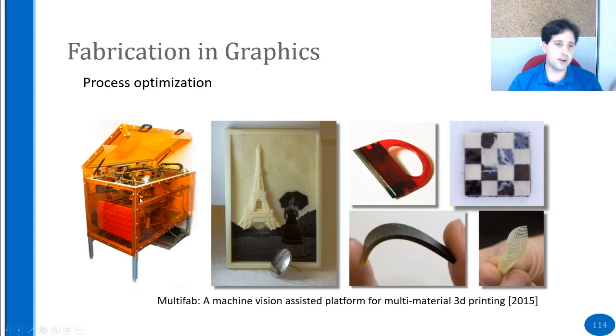Now, because this is a low-end, low-accuracy machine, some droplets didn't land correctly, or a bit too much of the fluid came out, or the position of the head wasn't very accurate. And what this vision layer does is it looks at the geometry and what actually happened in the print, and then it knows for the next layer how to compensate for it. And through that, they got very, very high quality accurate prints using very low cost hardware. So I think this is a very interesting example.